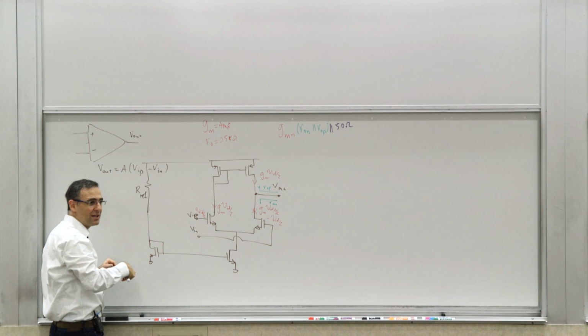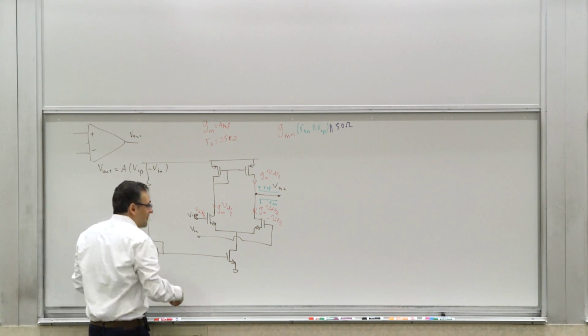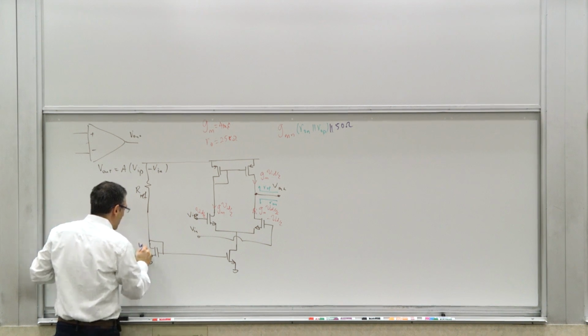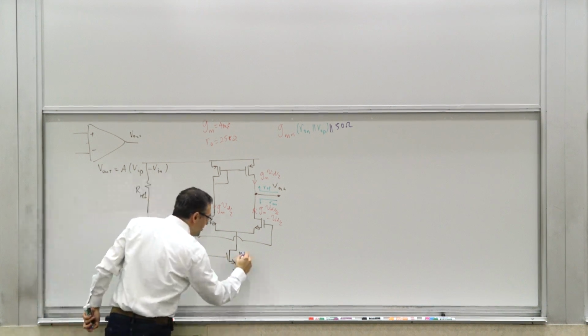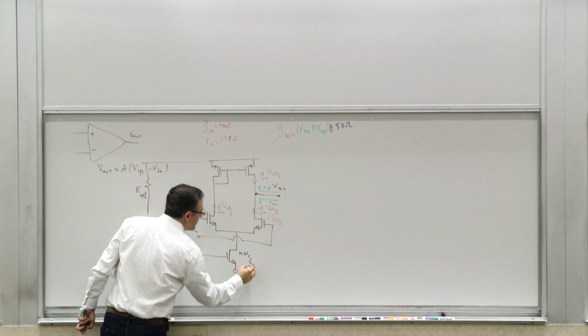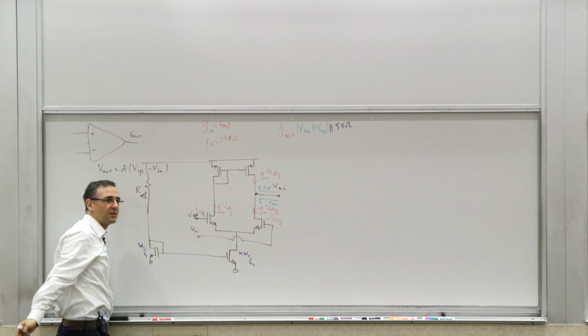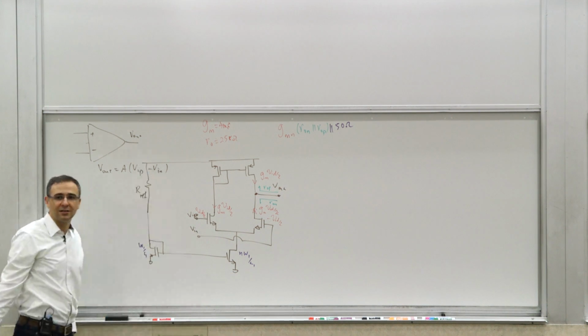It sets a reference branch, etc. So normally, you're not really done with the design at this point. So you have to say W1, L1. So this is going to be N W1, L1. Why do you want it to be larger? Because you don't want to draw the same amount of current as your main branch, because you will be wasting all of this current, right?